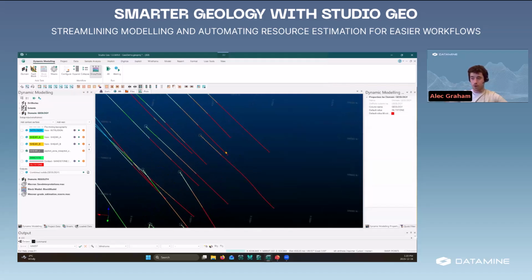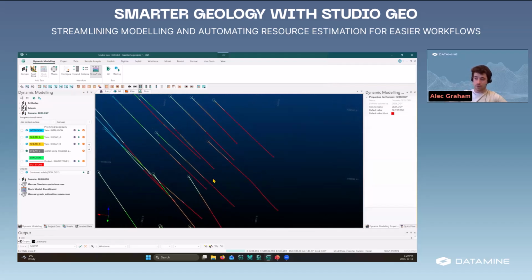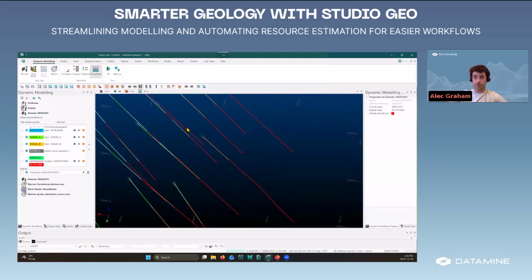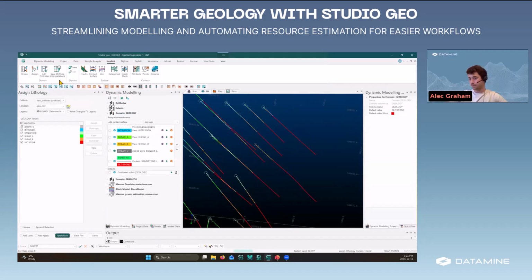If I would like to alter my data in any way, I do have the ability to code my data interactively in the 3D window. For example, when I go to my implicit ribbon, two of the tools that I'm able to custom code my data for modeling purposes are my assign and my group tools. So I'll do a quick example with the assign tool. When I open up this tool and I've selected my drill holes and I've selected that lithology field, it's already auto-populated for me.